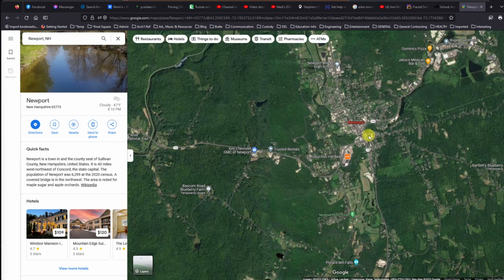Let's say it's a more complex project, and we've got a timber frame that is being considered. Timber frames have a special case where you have joinery, and joinery is not easily engineered. Is it just a fabulous way to build? Yes, it's very strong. And then we've got to find out the seismic zone, that sort of thing. And then find out if wherever this property lands, city or county, that piece is going to require the stamp of a PE, or a professional engineer. In this case, that would mean a structural engineer.